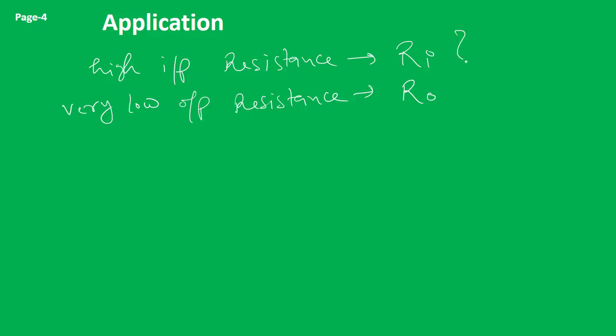So here we are getting voltage gain less than unity, whereas we get sufficient current gain, that we have seen from gamma. Therefore this circuit is seldom used for amplification, but because of its relatively high input resistance and low output resistance, it is used for impedance matching. What is impedance matching? Suppose we have some device, say this is my device 1 and this is my device 2.